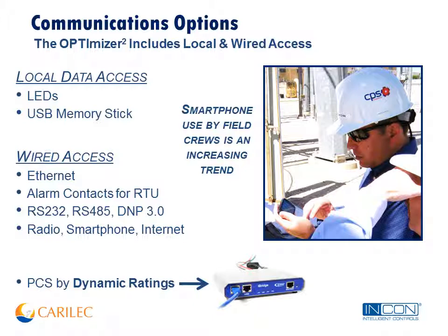As I mentioned, we have local data access via some LEDs, USB memory stick. Wired access would include Ethernet, alarm contacts for existing RTUs. You can use serial 232, 485. You can use both of them at the same time, talking DNP3.